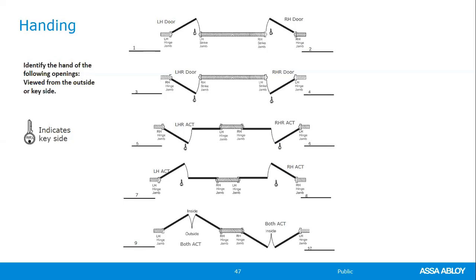In commercial hollow metal, we have 4 different swings for the door. The reason is that not all of the hardware holes, when we're prepping that door, go through both faces of the door at the same location. So we need to know what we call the true swing of that door in order to prep it correctly.